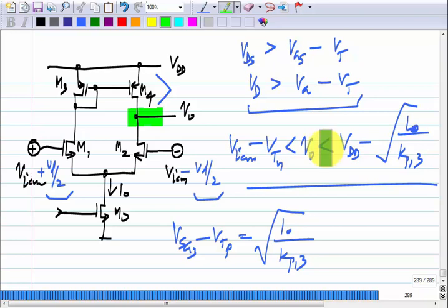This is because always you will have some component, some transistor between the output and VDD, right, and you have to have enough voltage across that device. The best thing you can do is have just one transistor between the output and the rail. Okay. So, in fact, here between the output and the upper rail there is just one transistor, you have to leave room for just one transistor. So, it is optimum on the upper side, but on the lower side you have two of them. So, this does not go very close to ground at all, but it goes quite close to VDD.